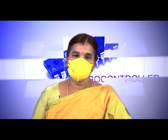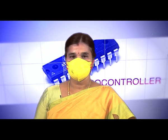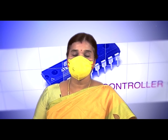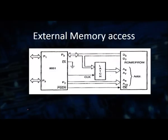If you want, you can extend the memory capacity up to 64 kilobytes. While extending, or if you want to access the external memory, you have to activate the external enable bar. This diagram clearly shows how to interface the 8051 with the external memory. Generally this is a ROM which has a number of address lines and then data lines. The data lines are bidirectional lines. We can send the data or we can read the data. Then we have 16 address lines, so the maximum capacity is 64 kilobytes.